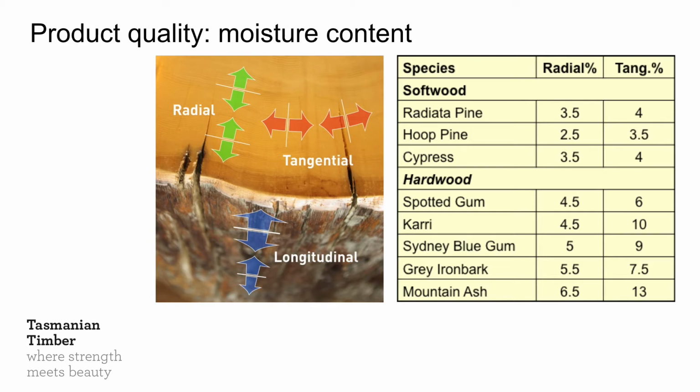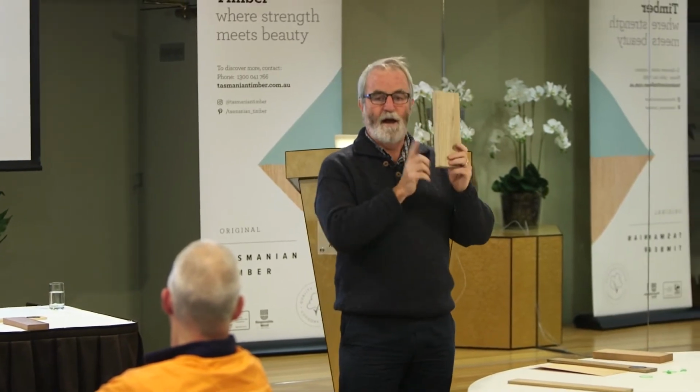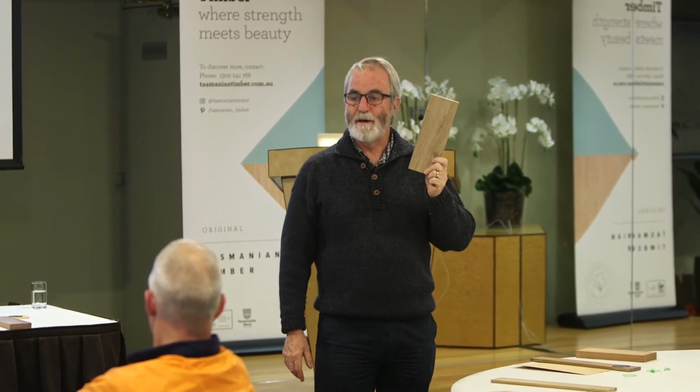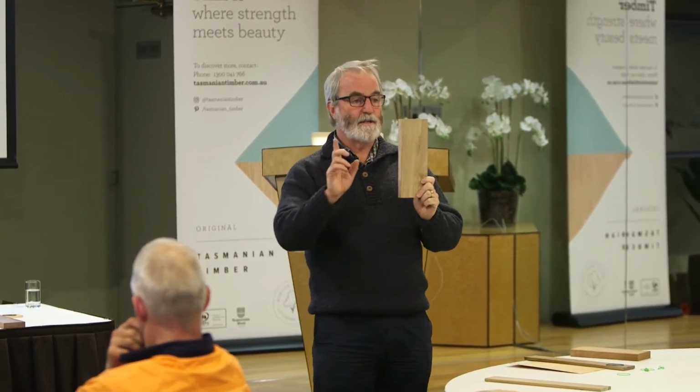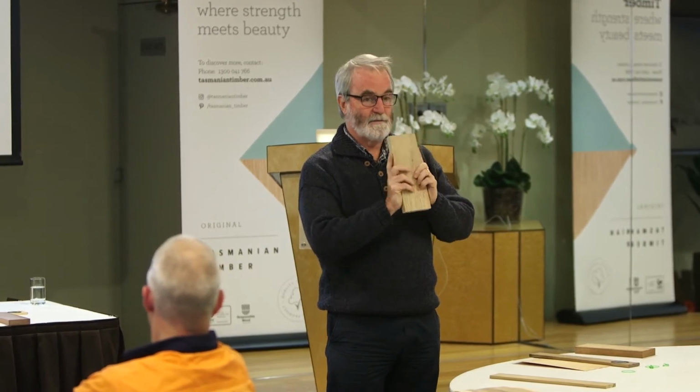Radially, it will shrink 6.5%, tangentially up to 13%. So if my milling colleagues want a piece that's 100 at the end, they cut it at 115, something of that order, knowing that it's going to shrink that much down as it dries.